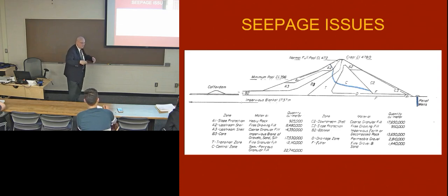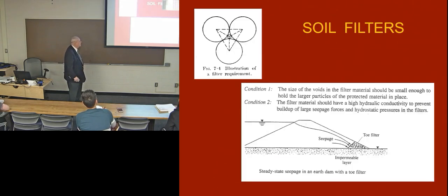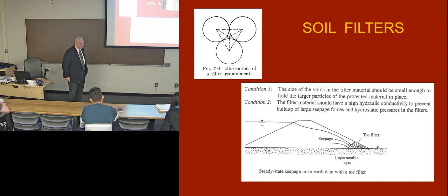The more equal potential lines before you get to a critical point, the lesser is going to be the hydraulic pressure. This was the purpose. So we're going to see a little bit more about these two issues as we move along here. Okay, soil filters. Critical in the design of this dam and in some of the failures that have occurred in other dams, the filter effect has not been taken into account, and piping has occurred.